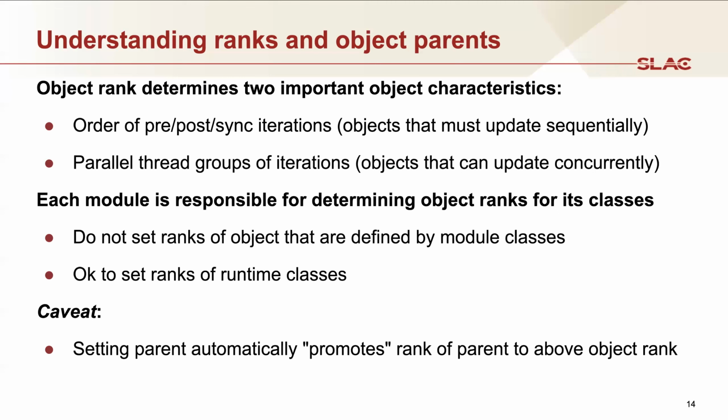There's a question here about how ranks are different from one module to another. For example, if we are using a forward back sweep, and we'll talk about this a little bit later when we talk about the power flow solvers, the ranks are what determine the sweeping order. So the swing bus, for example, would be the highest ranked object, and load buses would be the lowest ranked object. The forward back sweep method sets all the ranks such that the sweeping algorithm works correctly within that particular solver method. However, if you're using a Newton-Raphson solver, the ranks are set differently.